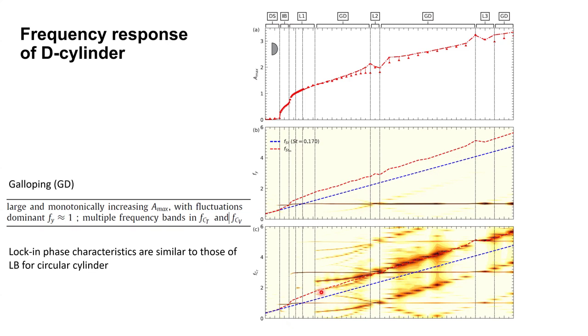So this red signal, the dotted red, matching with the dominant frequency is actually showing that the cylinder motion in galloping is locking to its modified natural frequency, not the previous Strouhal frequency. Actually, it's the modified Strouhal frequency. Now you can see certain things here. The dominant frequency keeps increasing.